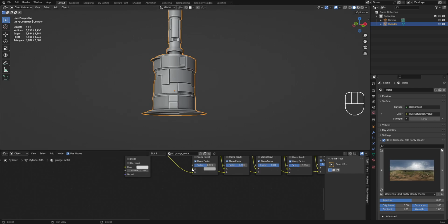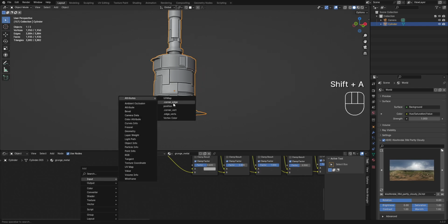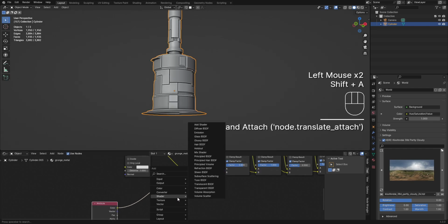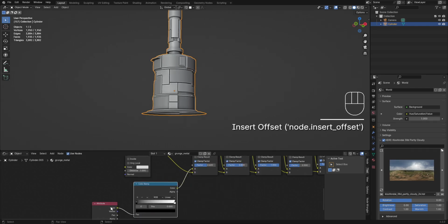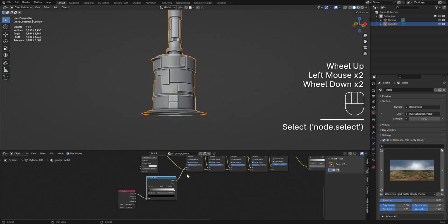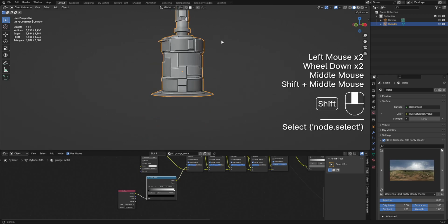So you can decide to use your own image texture, or the vertex color we created earlier, which is named vertex color, and connect it here as the color. Then we're going to drive the factor using the color ramp. If you're using colored or saturated colors for the vertex color, do not use the color ramp. It will transform that to black and white.